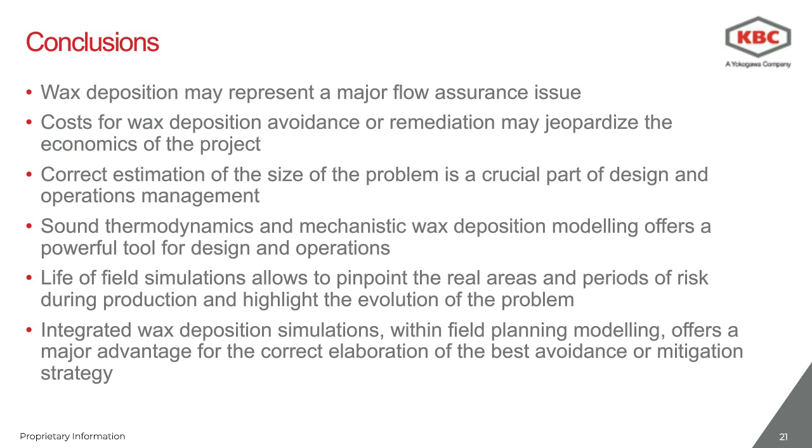And in particular, we have shown that what seemed to be an increasingly problematic issue at the end of the life of the asset actually turns out to be a problem which fades away as the production goes on. And even in the areas of high risk in the first 7 years of production, we've seen that the wax deposit is barely affecting the hydraulics of the system. So perhaps this could be a case in which one could live with the wax deposit, or pig once in a while just to make sure that the wax is not building up.